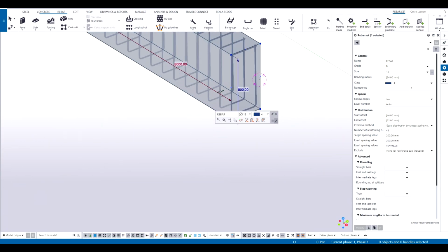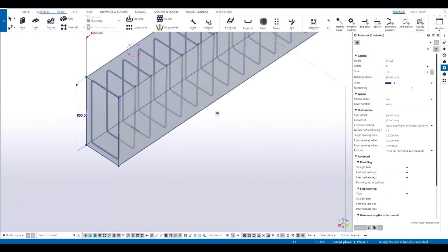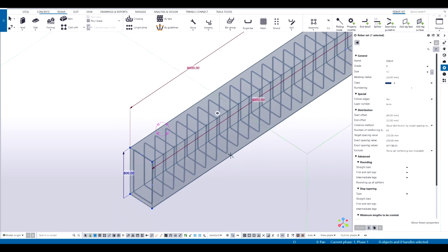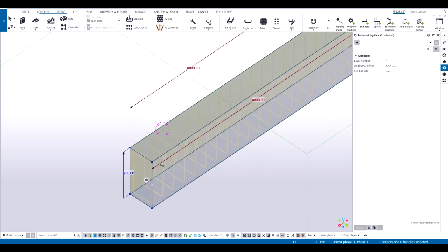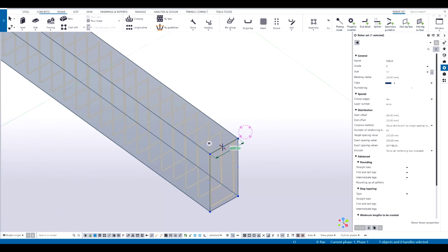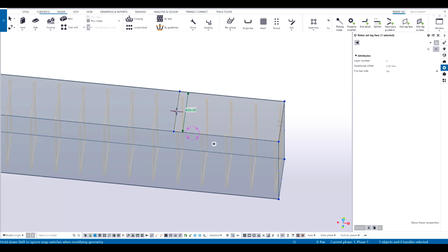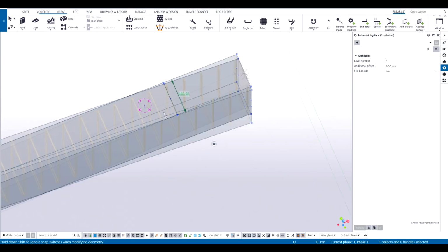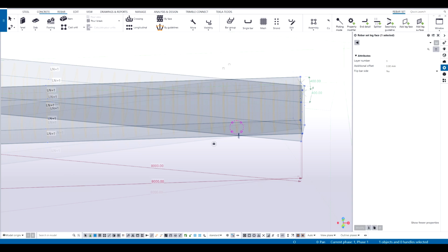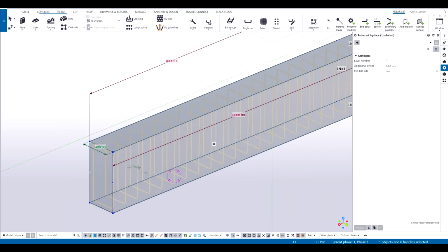Now what happens is, each of these leg faces is basically telling Tekla that it needs to have a rebar along this face, and you can select these faces individually. So if I now, for an instance, select this, see this view updated, and I move this back, you see, up to the place where it had this view, it's covering it. But from the place where I don't have that, it won't do that. So this leg face is basically just attached to the surface, and that's how Tekla knows that it has to draw a rebar over there.